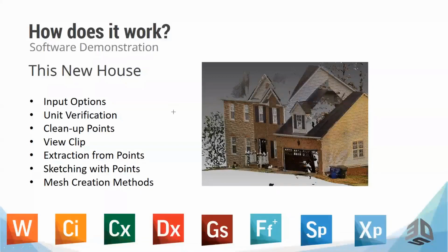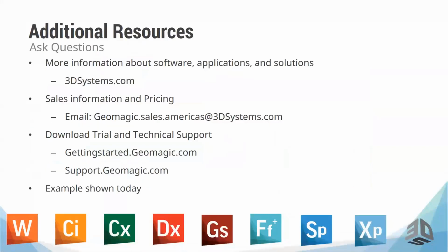There isn't really an upper limit to what the software can handle. I pulled in point clouds that were hundreds and hundreds of millions of points to work with. It's more usually just graphics intensive at that point, where you have to turn some things down and use some of that clip tool to make your life a little bit easier. Again, working on getting rid of data you don't need and working on like a scan-to-scan basis can generally speed up the process too and make things a little bit lighter for you.